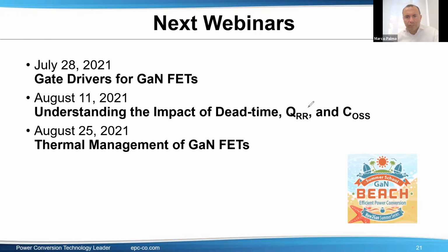Why is the hard switching gate loop more critical than the one for the GaN acting as a diode and risking induced turn on? The hard switching, let's put it this way, depends on the application. But when you're doing hard switching, imagine you have a low side recirculating, because you switched the channel off already, and the current is flowing in reverse conduction mode, and then you switch on the high side.